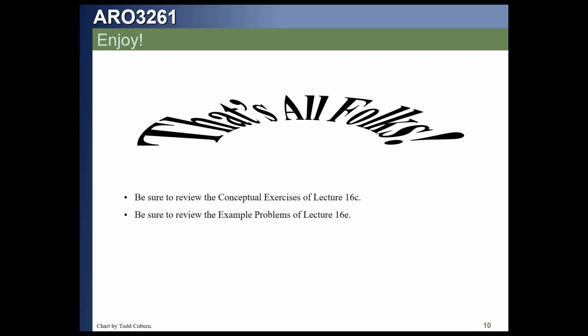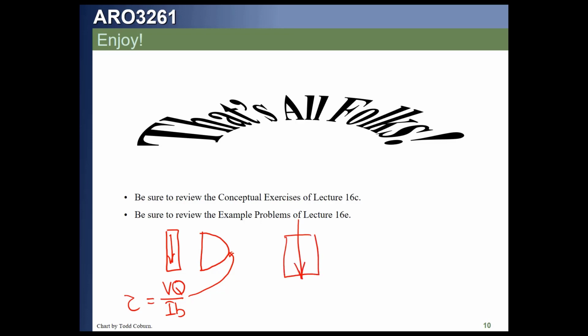We covered transverse shear on a cross section, which basically means if we have a section with a shear, we're going to need the V and the I and the width to get our shear stress, and we're going to need the Q, and that Q means that our stress distribution is going to build up in a parabolic fashion like this on a rectangular section with the maximum occurring right there. You'll notice the path that we're taking on this section and all segments we covered was top to bottom.